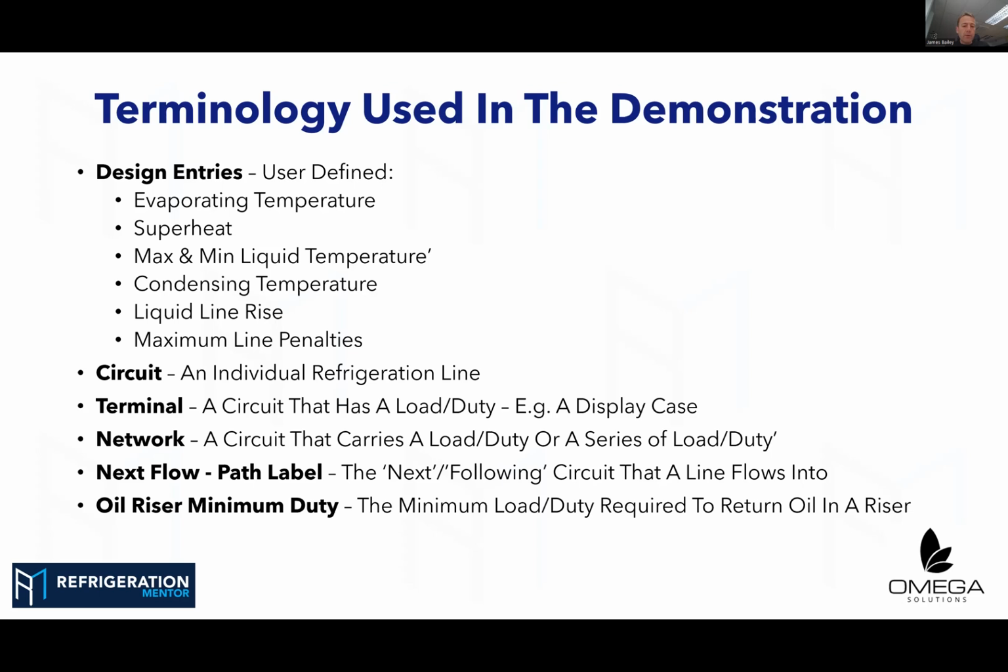The great thing about White Rose software is we could set a penalty at 1 degree, at 1 Kelvin. So effectively, we're going to hit an SST of -7 and not -8. The difference in that 1 degree can be a 4% energy saving, which in a refrigeration system, especially when you multiply that out on larger systems over 15 or 20 years, can be quite an incredible saving. And as I say, I think that's in week 3 of the demos.